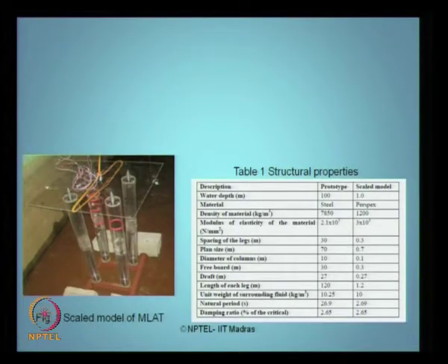Of course, the density of the material and the modulus of elasticity have all been scaled. The size of the platform attempted here is 70 meter square, which conforms to around 0.7 meter for a scale of 1:100. And of course, the free board, draft, and length of the leg are all available to us. The free vibration test was conducted, and we found that the natural period is close to around 2.7 seconds for the model.